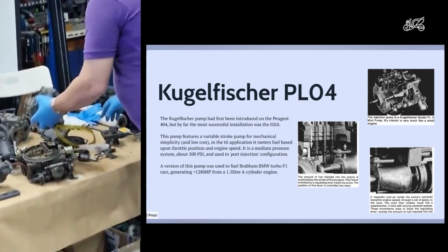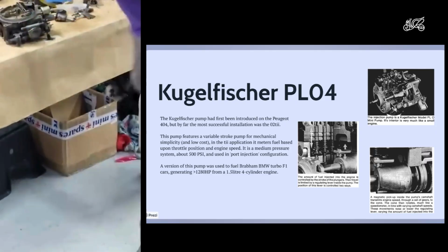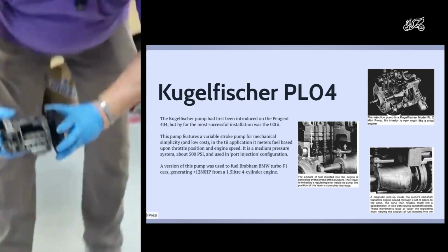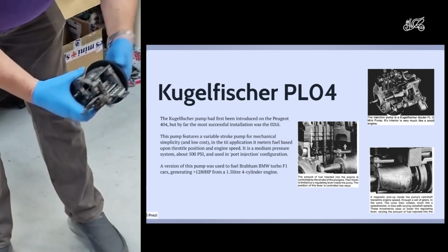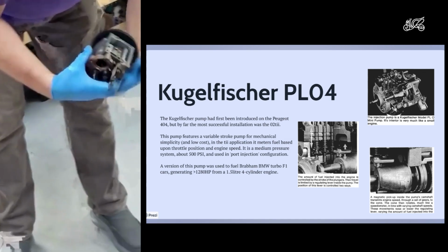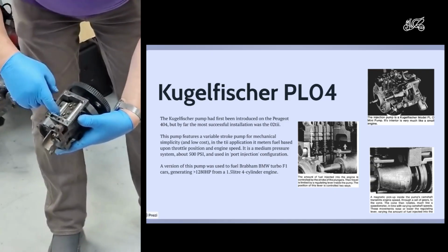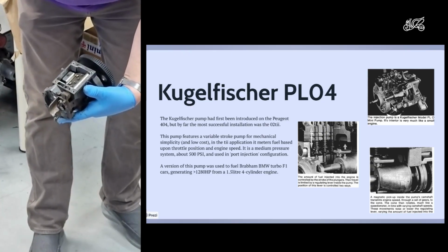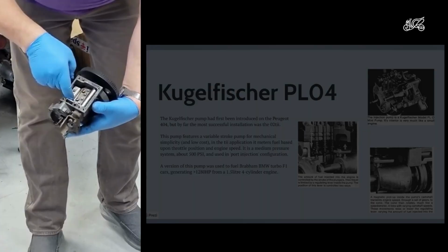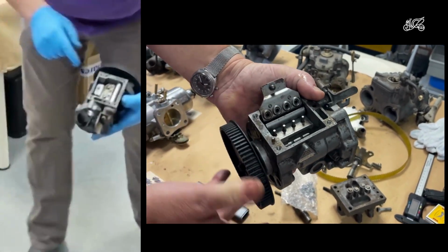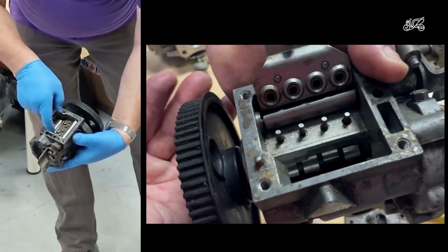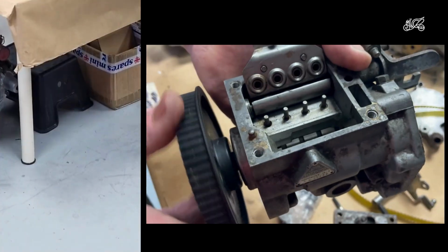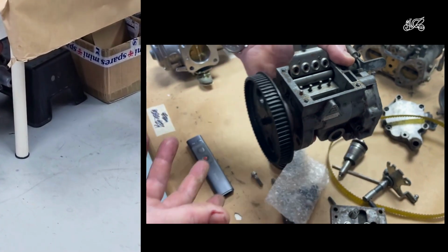And then inside the pump body, there's a cam. I don't know whether you can see that turning down there. There's a cam, and that's moving these little pistons the same each time. And this plate is what, as I said, you need to restrict how far those pistons come down. It's done with this plate. Yeah. Okay, so now I need to control the height of this plate. So the height of this plate controls the mixture, basically. That's the way it works. And I do that with this funny looking cone.